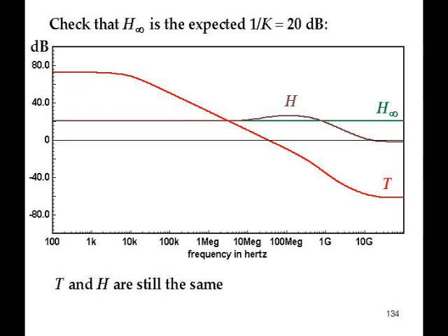And the closed loop gain H peaks up a bit and levels off again just below 0 dB at infinite frequency. Now, I haven't mentioned much about what the final H is yet, but notice I did mention that the loop gain had a phase margin of 87 degrees. Therefore, the apparent peaking in H is nothing to do with an inadequate phase margin. Normally, you'd make that association.